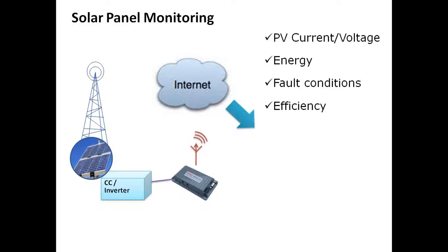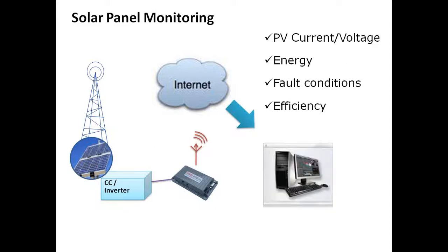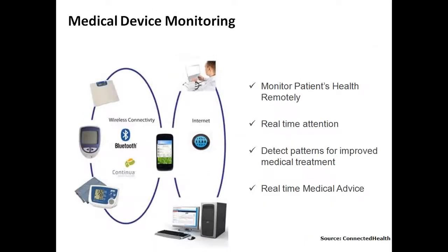This is just you open it on a web browser, and you would potentially see the fuel level at that time in the DG, and you can also see the DG status, is it on or off, DG runtime. You could also see the runtime for the entire day, or you could potentially get historical runtime information. Those kinds of things are typically what you would see in this DG. You could also enable this backend system or the monitoring device to send you alerts such as SMS or email alerts to make sure that you get some alert parameters either when a fuel level falls inexplicably and in terms of theft, or battery level falls below a certain point where it needs maintenance.